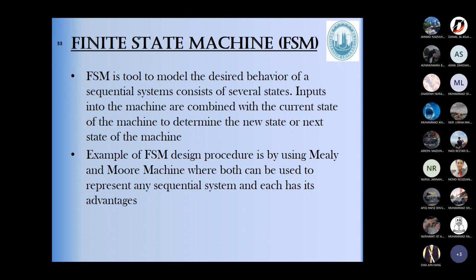Okay, so FSM is a tool to model the desired behavior of a sequential system consists of several states. Inputs into the machines are combined with the current state of the machine to determine the new state or next state of the machine. Okay, so input will be a very important part for this FSM lah. Okay, if you remember clock, for counter input yang paling penting adalah clock. Itu saja. But this one you need clock, and then we need external input to determine what the state will be and what is the input and output it becomes.